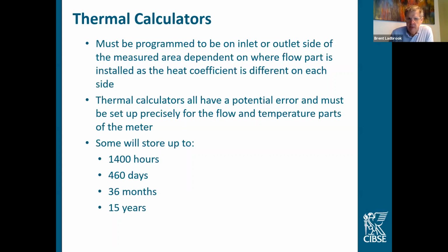If that is a variable temperature, it's looking up to every 2 seconds on a mains powered supply unit. So every 2 seconds as a minimum, it's looking at the temperature, looking at the recorded flow and adjusting that K factor. So if that moves even minutely, it'll use the appropriate K factor at that time.